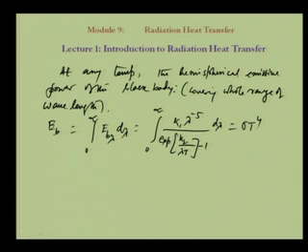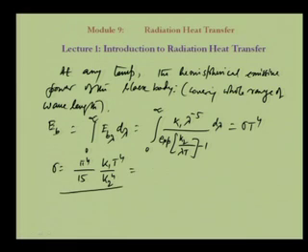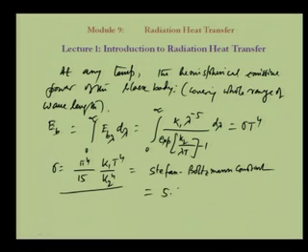There are some references from where the integration can be seen, and here that sigma is basically pi to the power 4 by 15 capital K1 by capital K2 to the power 4, and here it is T to the power 4. So, this is the expression for sigma, and we know that sigma is called Stefan Boltzmann constant, and its value is equal to 5.669 into 10 to the power minus 8 watt per meter square per Kelvin to the power 4, where T is in Kelvin. Okay.